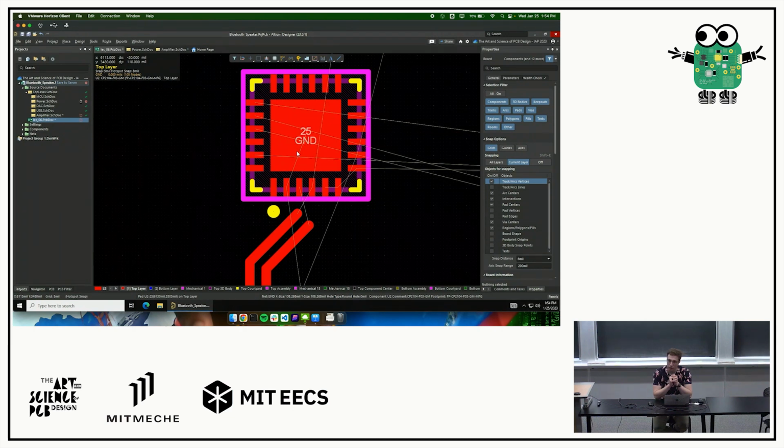Maybe you don't want to do that depending on what else is coming out of that chip. Maybe you do. It depends what the advantages and disadvantages of putting that chip on the bottom side of the board are. Here, if you were to do it, you would have to put two vias right where the connector are to go through the board and then route the differential pair that way. I don't actually know what the signal integrity implications of that are, but... Go ahead.